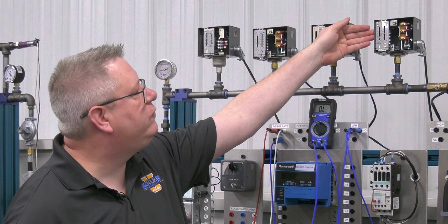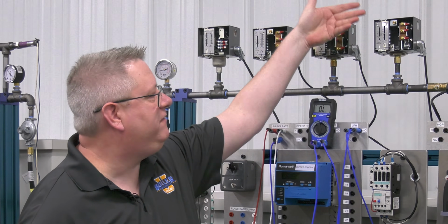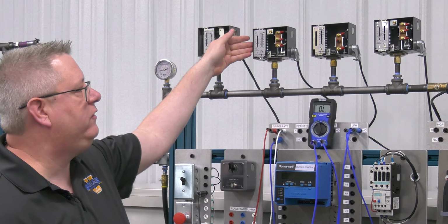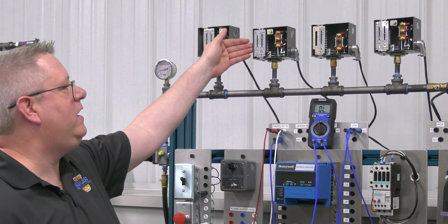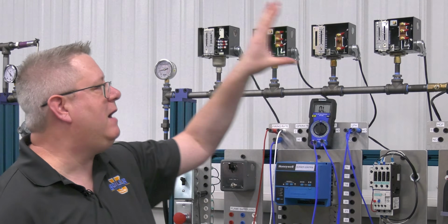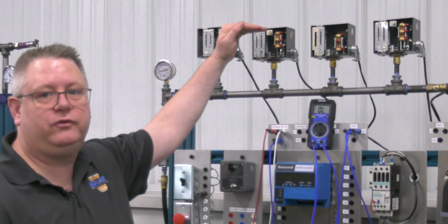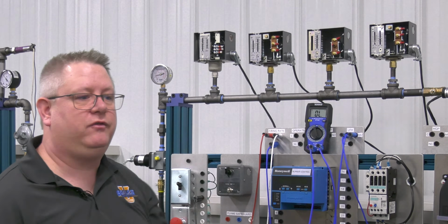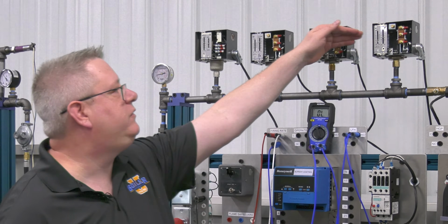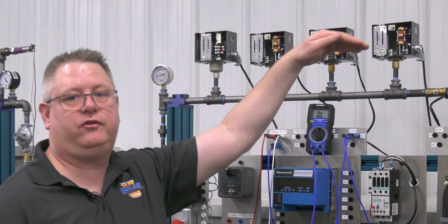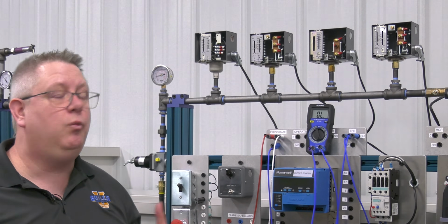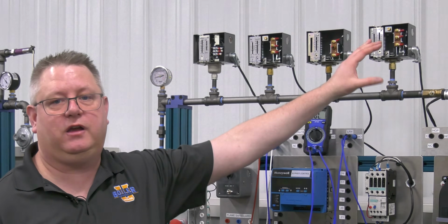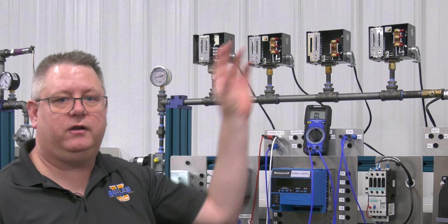A low fire hold switch is typically, in fact, identical physically to our operating pressure switch. These are the same model switch, and we can use them for either application using the normally closed contacts for a pressure device or usually the normally open contacts for a firing rate limiter. So the same adjustment and differential rules will apply. And once again, we always want to be looking at the gauge when we set these because they're just not super accurate.